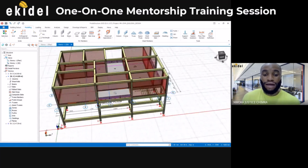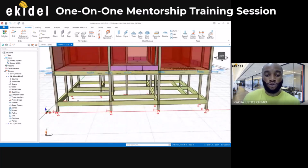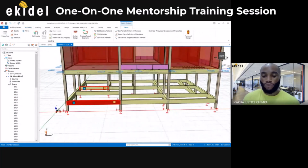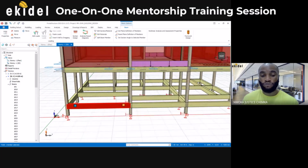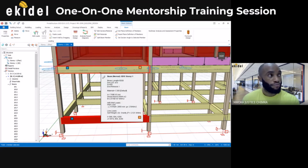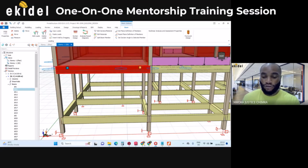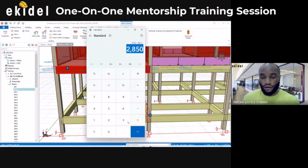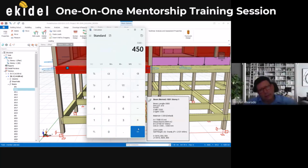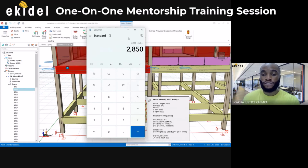So now we can actually choose to add our wall load again on this level. All right, that's the block wall load. So again now, this level here is 3.3. That's the height of this level, 3.3 minus 450, which is our floor beam, which is here. That gives us 3300. Can you hear me? Minus 450. Yes, yes. That gives us 2.85 again.